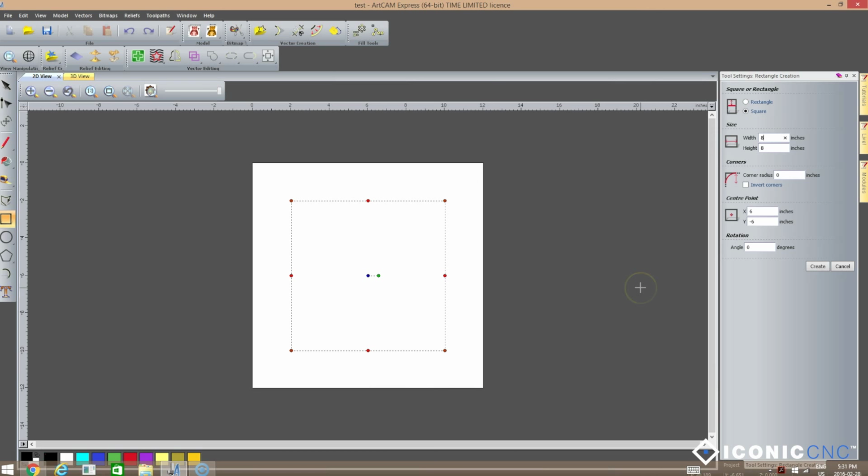So if you're positioning something on the workspace, you have to remember that you are working in minus coordinates on the Y. If that's not comfortable for you, if you'd like everything to be positive values, then you would have to set your reference point or your origin position in the bottom left. And then if you can think of this being on a grid, everything in the top left corner of that grid, which is basically everything up here in the top left corner past the 0, 0, now becomes positive values. I don't really have a struggle with that, so I typically use the top left corner as my origin, and I live with the fact that my Y coordinates are all negative coordinates.